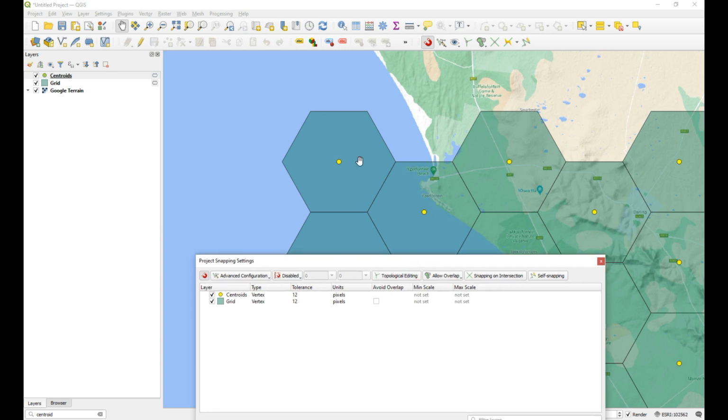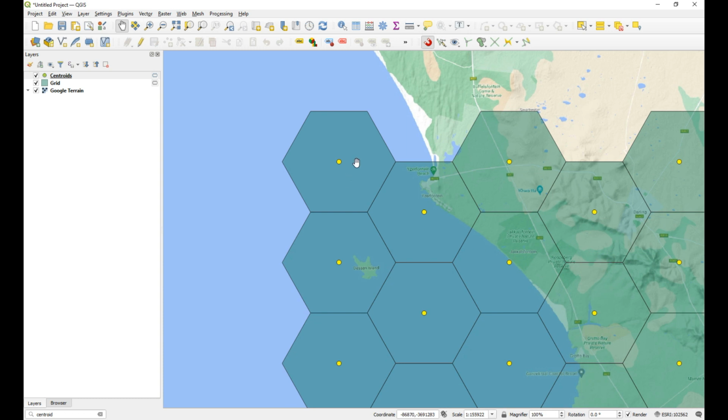We are just trying to work out what distance we should put in for our new grid line. So what I want to do is snap to the center point of this line segment. There is an option here: if you click under vertex, you scroll down and choose middle of segment, that will allow you to do that. So now you can turn that off. It should go off. There we go.